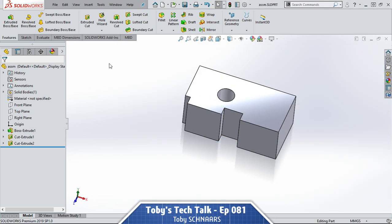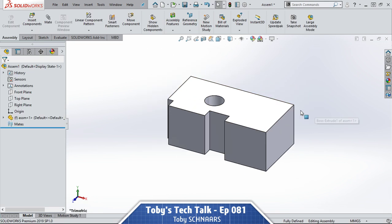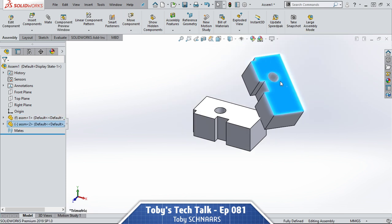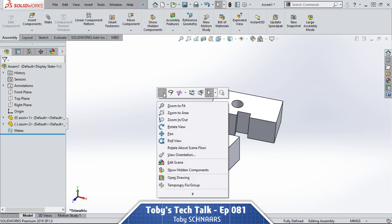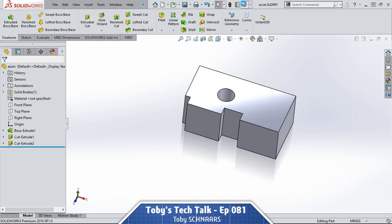And when you're in assembly mode, if you do a right mouse button and drag, that's how you rotate a model. So if I've got this assembly here, and I do a right mouse button and drag, you can see I can rotate that model. But that's also how we access the mouse gestures. So I would always find myself inadvertently changing the view by jumping into mouse gestures. Again, just personal preference.